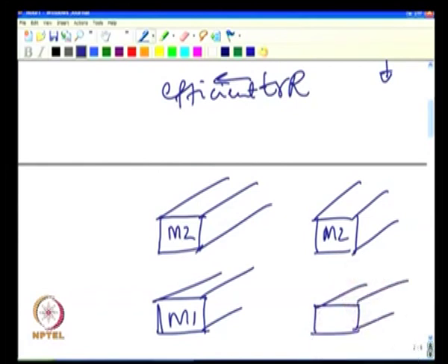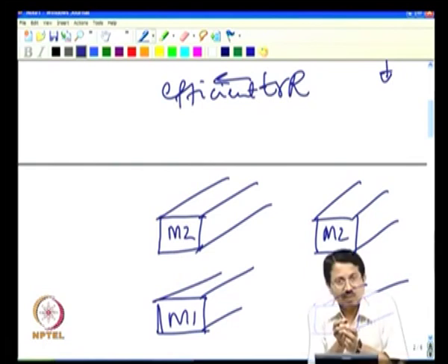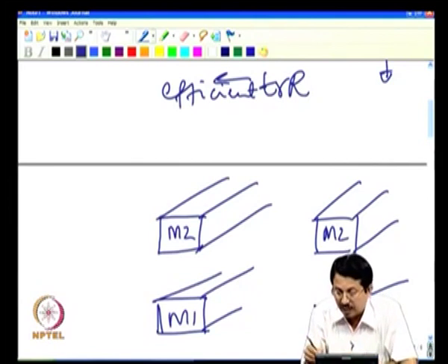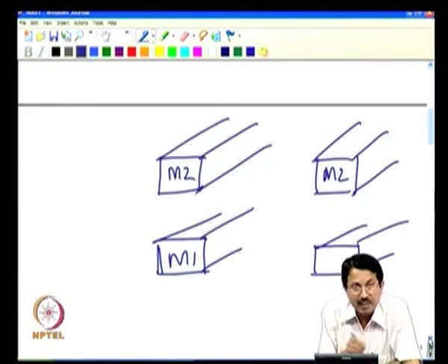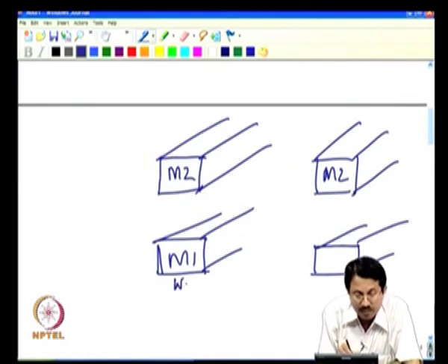What is scaling of interconnects? Scaling of interconnects is scaling the dimensions of the interconnect, just as the transistor dimensions have to come down and transistor distance has to come down, and the same here with the interconnects. The dimension has to come down. What is the dimension? This is the so called line width, we call it line width.